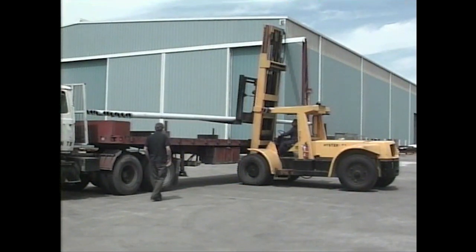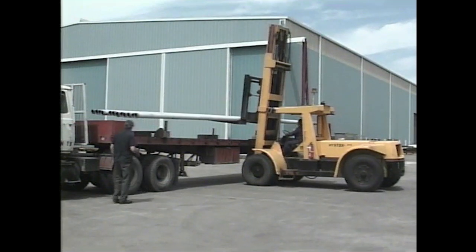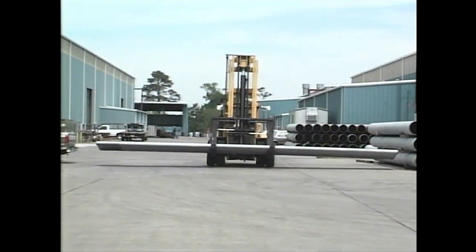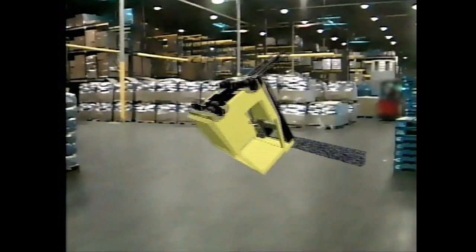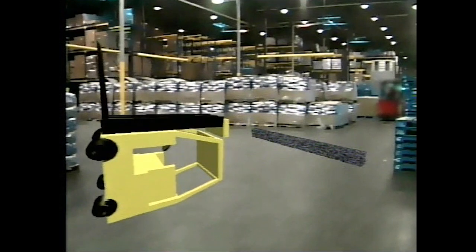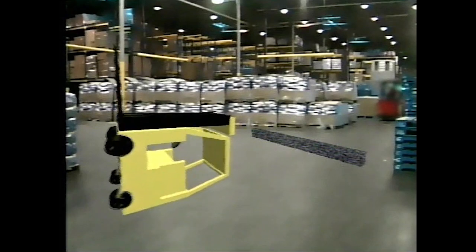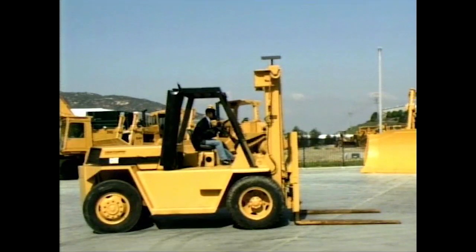Each class and size of equipment has different longitudinal and lateral stability principles, so it's up to you to remember how these affect your operation. A very short forklift would have less longitudinal stability than a very large or long forklift. Let's say you're driving a small, short forklift, and while traveling, you hit a 4-inch curb. Quite possibly, the longitudinal stability of this short forklift may cause you to overturn, whereas a large, long forklift would probably not tip over because it has much greater longitudinal stability.